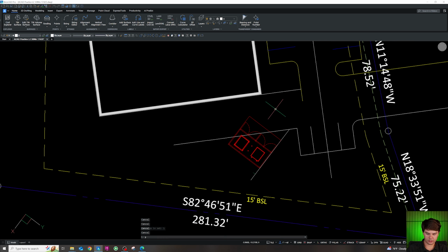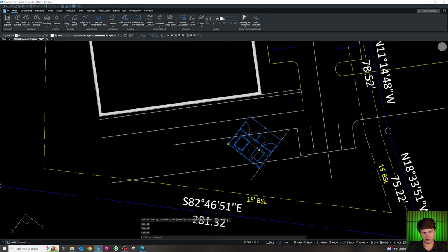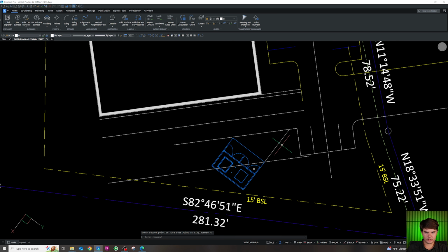We're gonna want a 30-foot drive aisle. Or we're gonna want 12-foot loading, 2 feet gap, 12-foot loading, a 30-foot drive aisle through here. So we want to make sure that our dumpster does not get in the way of that. Pull it down. Say about there is good.